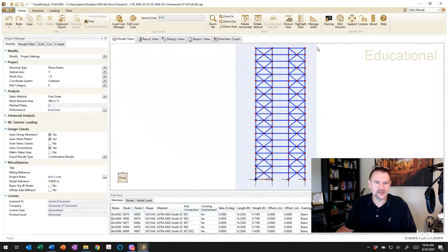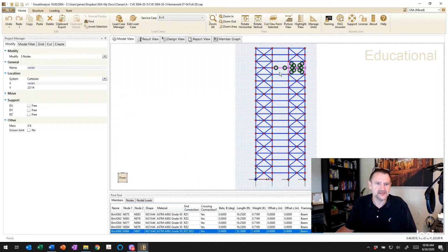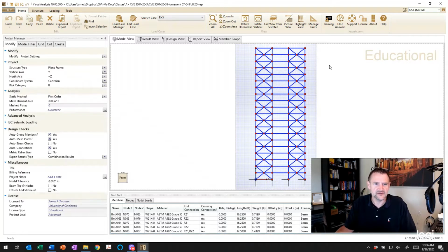If you do the same thing, but hold down the shift key and drag from right to left instead of left to right, then everything that's inside the window and everything that's intersected by the bounds of the window is selected. This is very useful if you want to be very strategic in picking different parts.